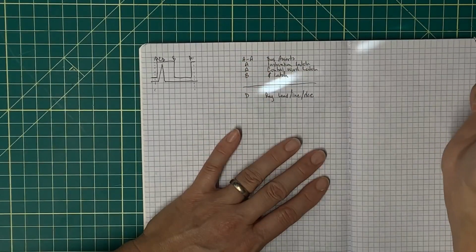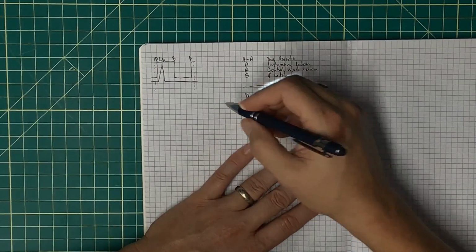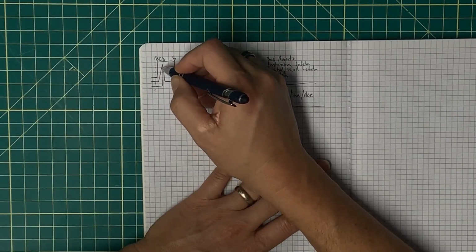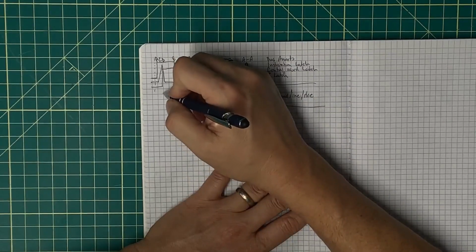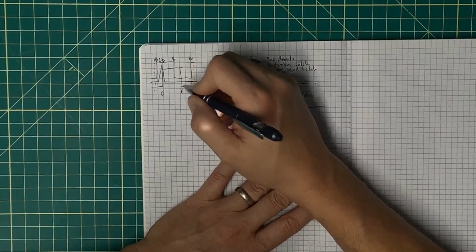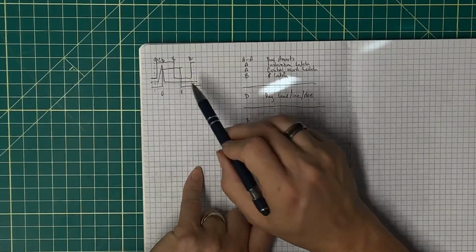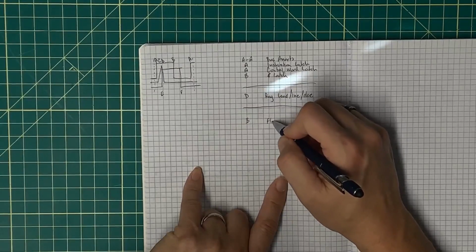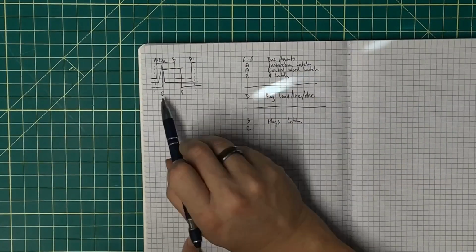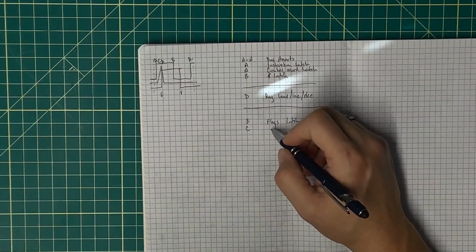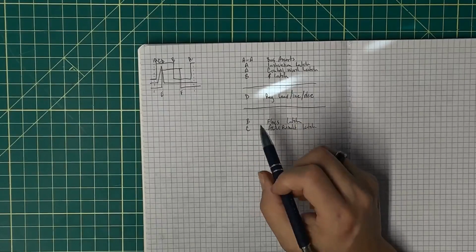And finally, I got into the ALU, and I have now added what looks like a delayed clock, where I now have transitions E and F, which have been added. So the ALU now has the flags latch also happening at B. At C, this rising edge transition here, I've got the ALU result latch.